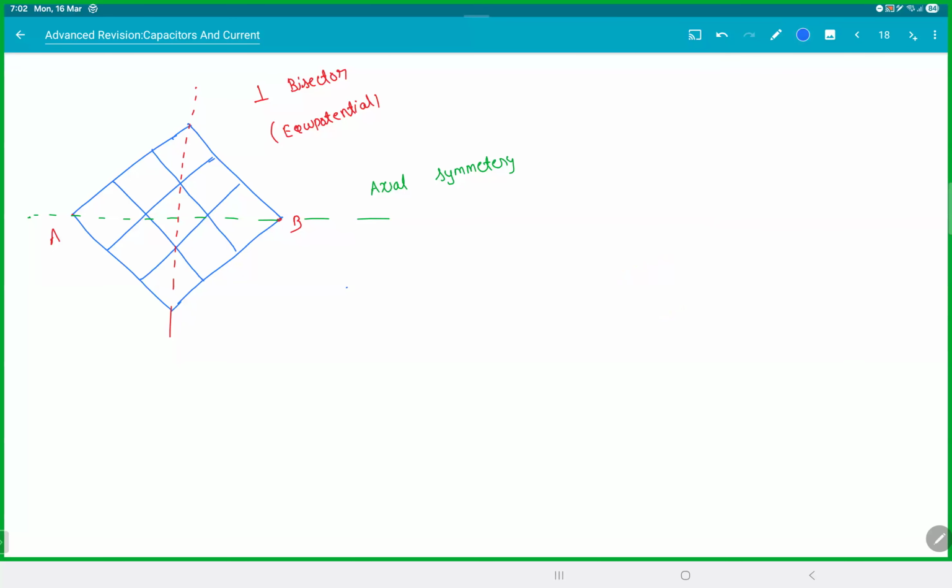And when you fold this, what will happen? Resistors, when they fall on themselves, when they're in parallel, resistance becomes R by 2. So this is how the circuit would look. This is B and this is A, right? So you'll get a half circuit like this. And each one becomes R by 2, R by 2, R by 2, and everything becomes R by 2 there. And one more thing about this bisector symmetry, they become equipotential, and next thing, all nodes can be opened up.